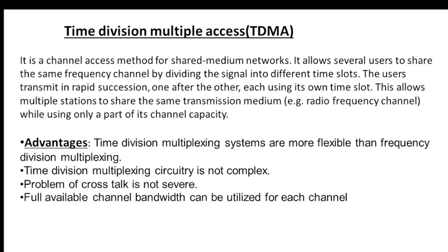TDMA is a channel access method for shared medium networks. It allows several users to share the same frequency channel by dividing the signal into different time slots. Time slots will be given for each frame. The users transmit in rapid succession, one after another, each using its own time slot. This allows multiple stations to share the same transmission medium, a radio frequency channel, while using only a part of its channel capacity.